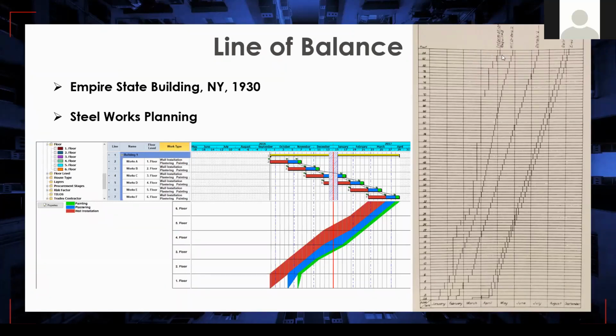Of course, in modern days, the line of balance charts are not created manually, and we can automatically update and display the line of balance charts within our software, which is planning and scheduling specific software, Power Project. What we see here is a Gantt chart. We have 3 activity disciplines with the codes. You see that the brown, blue, and the green ones are the wall, plaster, and the paint activities. And also we are able to track all these activity progress and also the productivity based on this floor information.